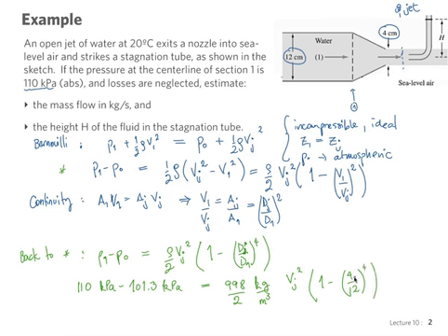And I can simplify this a little bit and write 1/3 to the power 4. So I can calculate that very easily now. Remember to turn it into, so this is 10 minus 1, so it's 9 minus 0.3, 8.7 times 1,000, 8,700 Pascal. That's our difference. We now multiply by all of these numbers and we can get Vj.